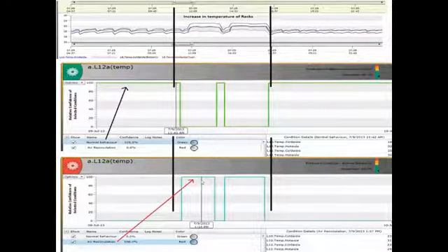The graph on the bottom says that this new state is identified, and we can associate that state with the removal of the number of blanking panels that we removed. And the system then has learned that. It says, well, this is the new state. It's abnormal, perhaps, by looking at the second graph, but it is identified as this particular state. So you can identify a number of states that you can simulate or preload, and say, when I see any of these states, I'm going to sound an alarm.